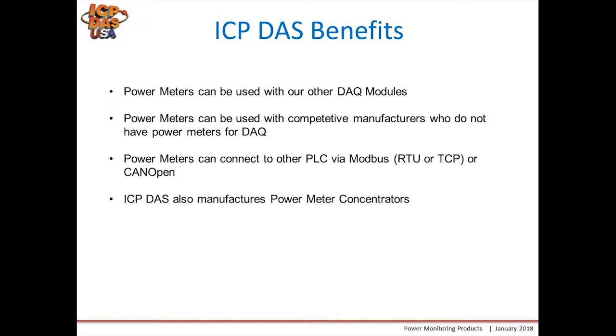The power meters can be used with competitive manufacturers who do not have power meters for data acquisition. The power meters can connect to other PLCs, both Modbus RTU, Modbus TCP, or CANopen. It doesn't necessarily need to be ours, so it works very well with third-party software and hardware. And we also manufacture power meter concentrators.